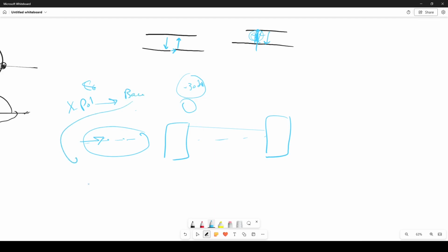And then this can be solved by, if you have the patch, I have the feeding here, and then here's the feeding. So we cover it by PEC, and then we shield around it by vias. So we eliminate the back radiation, and then we have everything here. So these solutions we can go through later.